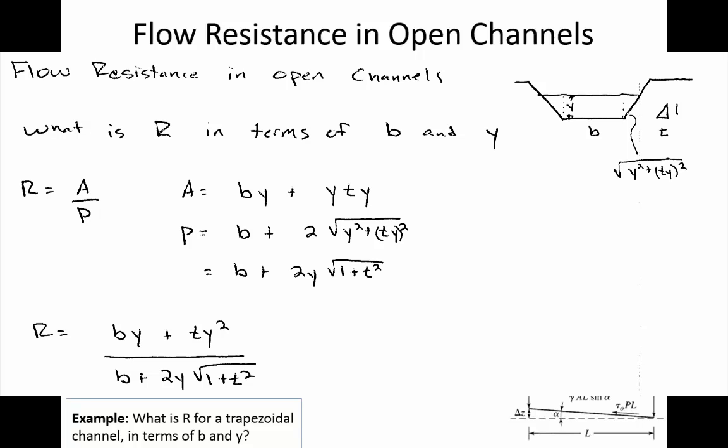All right. The wetted perimeter, though, is a little bit ugly because this bottom is easy. That's going to be in the wetted perimeter. Wetted perimeter for an open channel doesn't include the top where it's touching the air. You know, the perimeter of a pipe is just the physical perimeter of the pipe because the pipe is full of water all the way to the top.